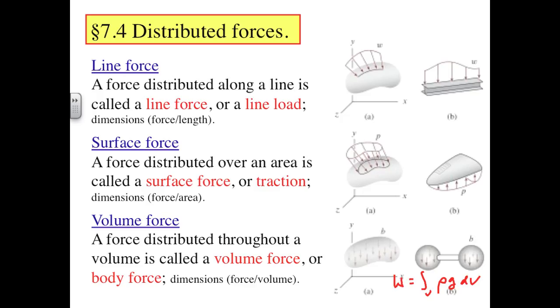Here we're going to use the symbol W again, but this is going to be a lowercase w. It's going to have units of newtons per meter, and this will be equal to mass density ρ times g, that's the volumetric body load, times A, where A is the cross-sectional area of the beam. And for this particular beam, for instance, if it's an I-beam, then the cross-sectional area would be the area of this section, looking at the I-beam from this direction.